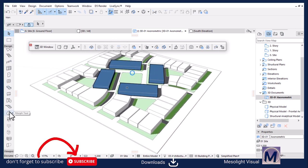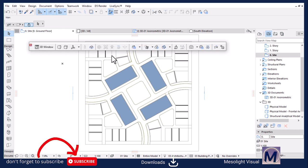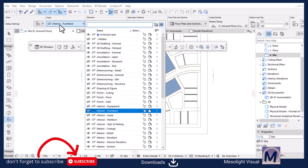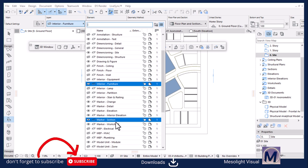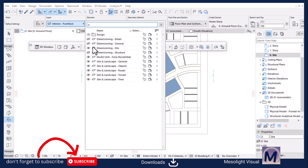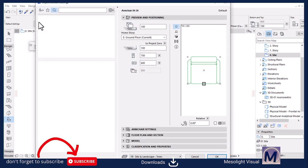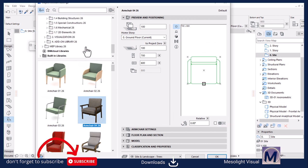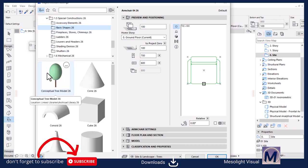So I'll go to object. Let's do it on the floor plan. I'll go to objects and then change the layer to site trees, and then open the object settings. Let's go to the folder called special elements, or basic shapes. There is this conceptual tree model.